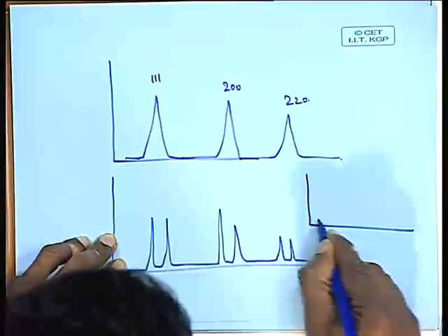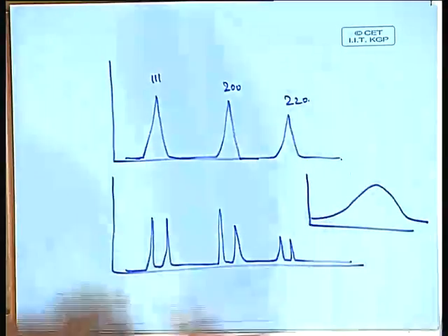And then immediately he started taking a number of other eutectics and thought every eutectic should give you a solid solution like this, and that is where he stumbled upon the gold silicon system. He took the gold silicon 80-20 eutectic alloy and rapidly solidified it, and interestingly what he got was an X-ray peak like this.